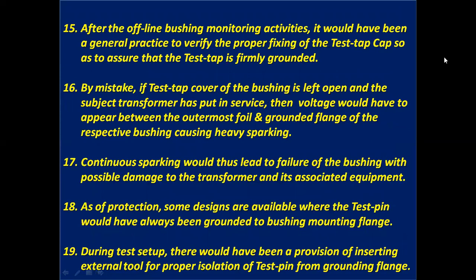Number 15, after the offline bushing monitoring activities, it is a general practice to verify the proper fixing of the test tap cap so as to assure the test tap is firmly grounded. Most important one.